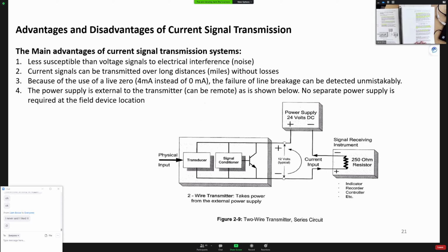Depending on the signal, there might be a positive or negative voltage created by the wire resistance. So when you reach the final equipment, the voltage signal is going to be changed more easily than the current signal, because the noise causes some voltage on the wire, but it's not going to affect the current too much.